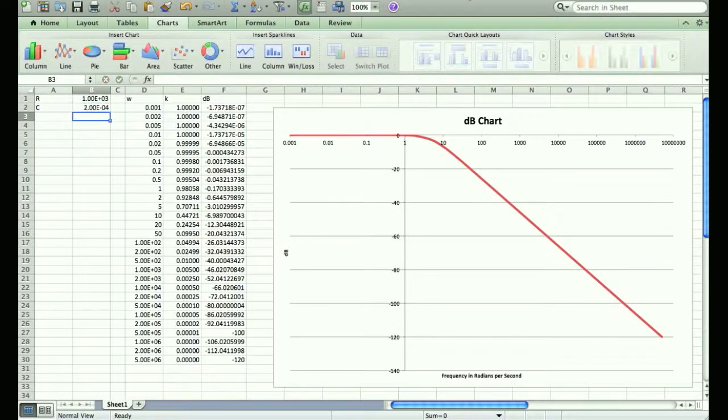You have three choices. I'm going to double the value of C. Is my cutoff frequency going to get higher, lower, or stay the same? I can't really expect you to know the right answer, but I want you to at least sweat it out and think about it for a second. If I double the capacitor, what's happening to my cutoff? Smaller.